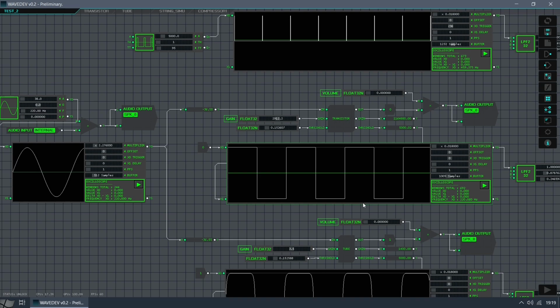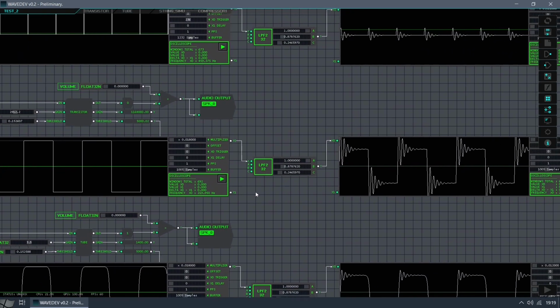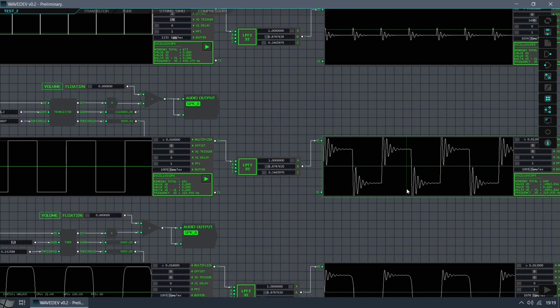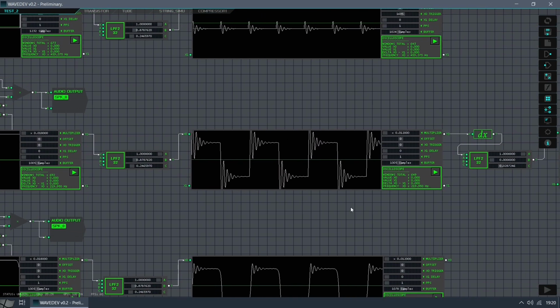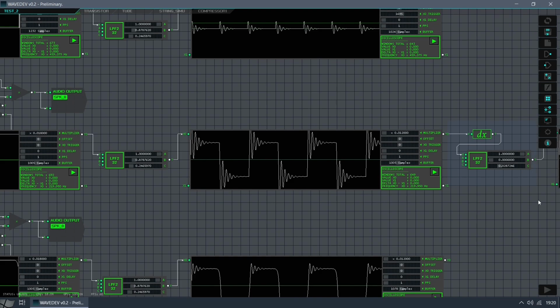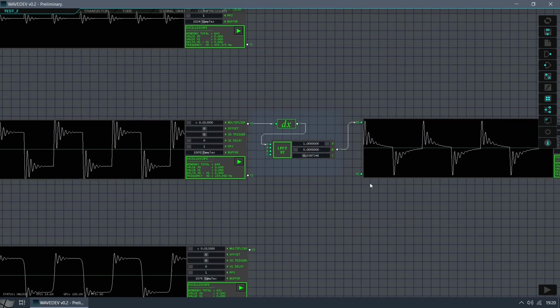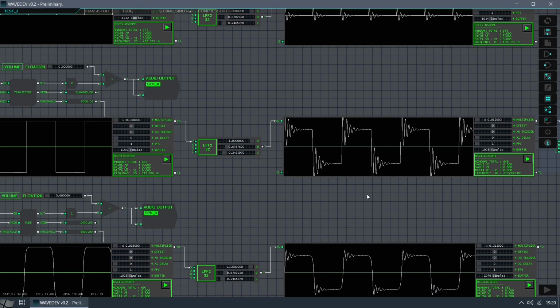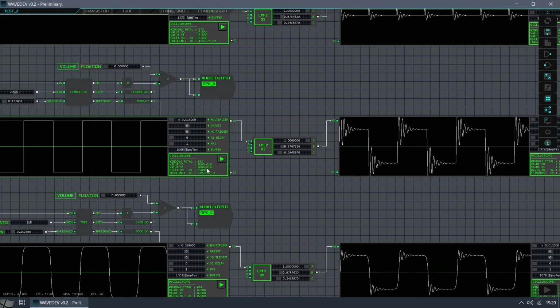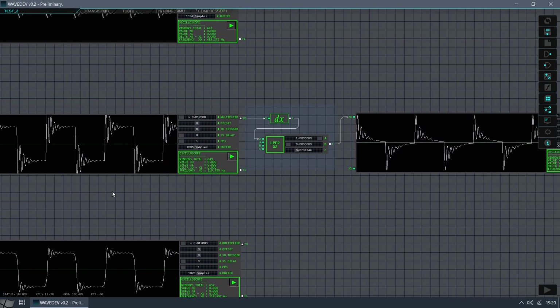Now, what kind of deformation are we talking about? Will this be it? Not quite. This waveform still has a continuous component that cannot be transmitted in the physical world. If we remove the continuous component with a simple high-pass filter, we will get a better approximation. That's right. If you send this waveform to your speaker, your ear will receive something like this.